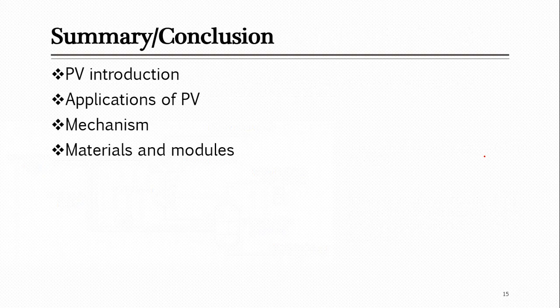So that's it. In this lecture we started with pervaporation. What is pervaporation? Pervaporation is a combination of two words, perm-selective and evaporation. Through this membrane we have seen that when separation takes place, after permeation of the liquid species, they get converted to vapor on the other side due to application of vacuum, or very low pressure as compared to ambient pressure.